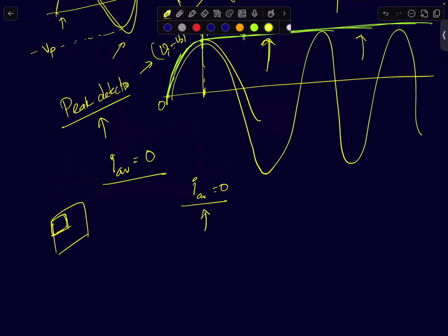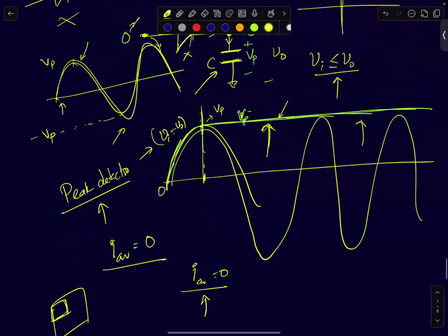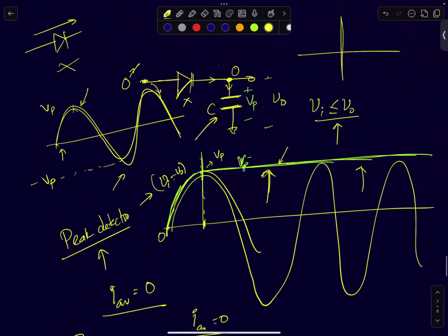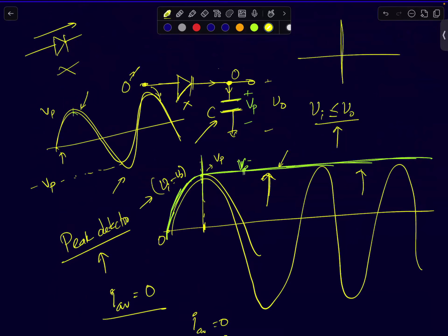If you put this device there, RF power, you can treat it as some kind of a sinusoid. You guys can imagine it like some form of amplitude modulated signals. Amplitude modulated signals are like a sinusoid. They have a very high frequency carrier. Amplitude is changed very slowly. So for all practical purposes, you can treat them like some carrier signals. From those carrier signals, I will use a very simple form of a circuit, some circuit like this, to extract a DC signal.